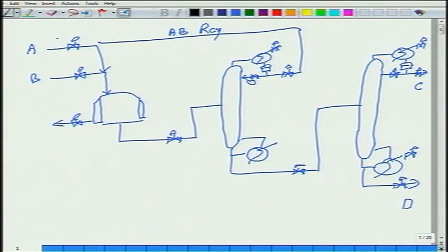Now I am going to have my throughput manipulator this way. Okay. So the set point, the fresh A feed rate, is the throughput manipulator. Now once the throughput manipulator is set, I can go downstream as well as upstream from there. Upstream there is nothing, or whatever is there is not in my scope. I just have to go downstream now, right?